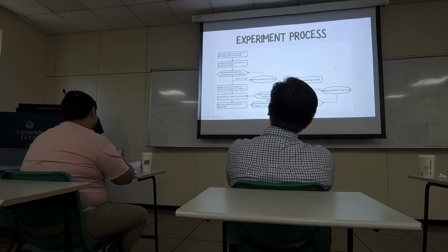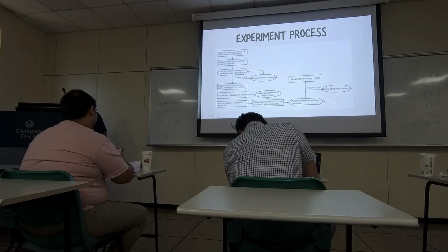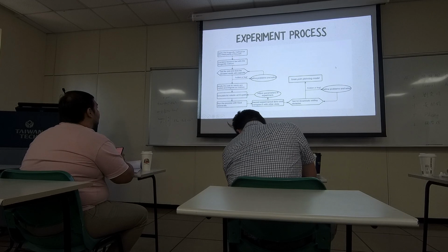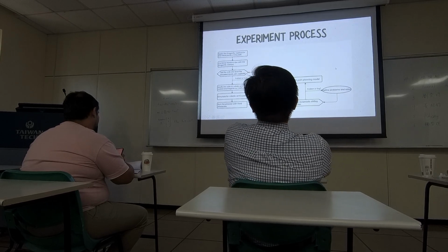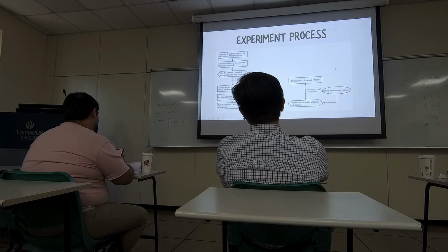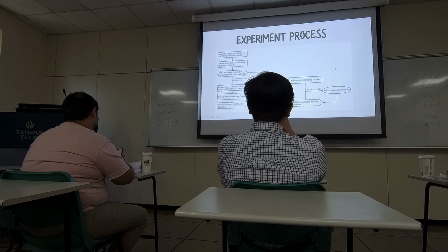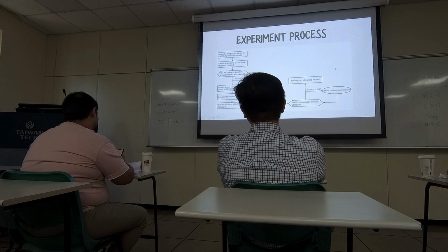Before running the process with big obstacles, we will simulate the robotic arm's path. Here, why do we use fixed obstacles? Because we think that using fixed obstacles is easier to debug the code and adjust the parameters. After running the process, we will record experimental data and adjust the parameters to do the process again. Then compare all the data and define the best parameters of the path planning. In the final part, we will test for the dynamically shifting obstacles, then finish the path planning model.